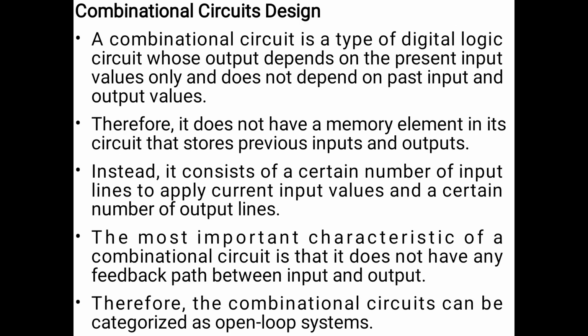Combinational circuits design. A combinational circuit is a type of digital logic circuit whose output depends on the present input values only and does not depend on the past input and output values. Therefore, it does not need any memory element in its circuit that stores the previous inputs and outputs.